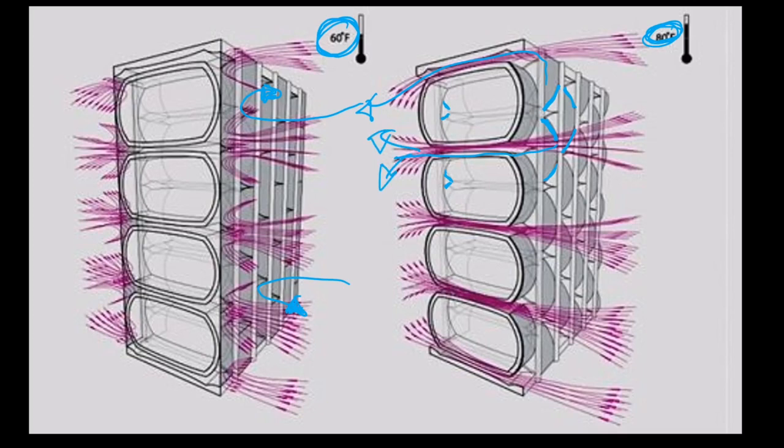But that's what we call passive ventilation. That's about controlling the heat loss in a building and cooling it down. What happened there is once it's got to 80 degrees Fahrenheit and it's all opened up, it'll maintain at 80. If it opens up at 80 and then it goes to 100 degrees, well, largely this will keep the building cooled to a certain point where you may have to have mechanical ventilation kick in at, say, 90 degrees because there's not enough airflow going through. But it's not a one-size-fits-all answer, but it certainly is a huge contributor to bringing down costs of ventilation and air conditioning with refrigerants and so on and so forth.